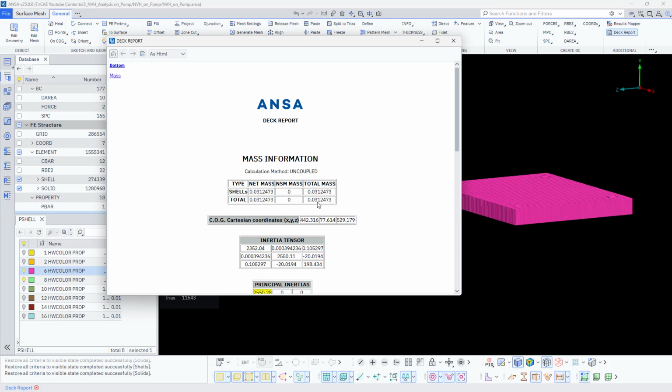We had seen that the stiffness curves at 265 and 310 Hertz were shooting up a lot. That might lead to a failure in a particular working scenario, so it is better to keep it low. So instead of keeping 5 mm thickness, I went ahead with 20 mm thickness, so that I could save on average 10 kg of mass.